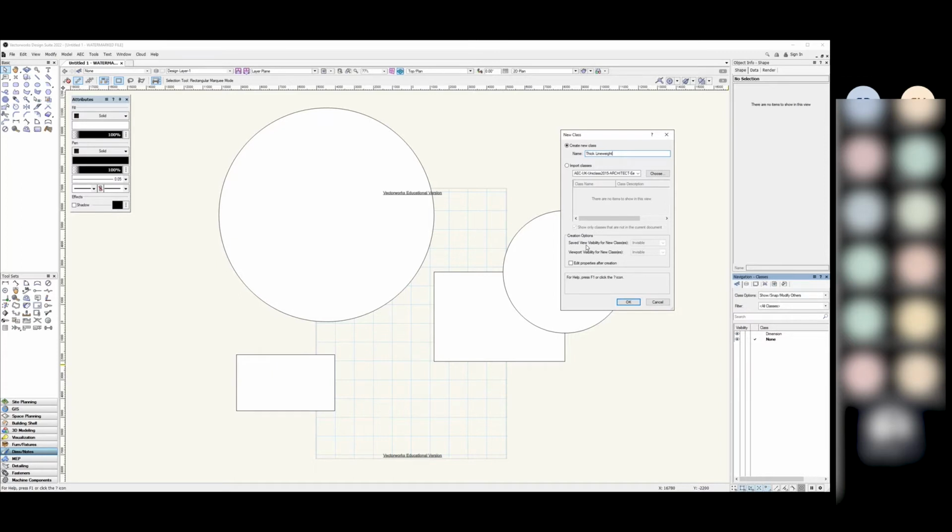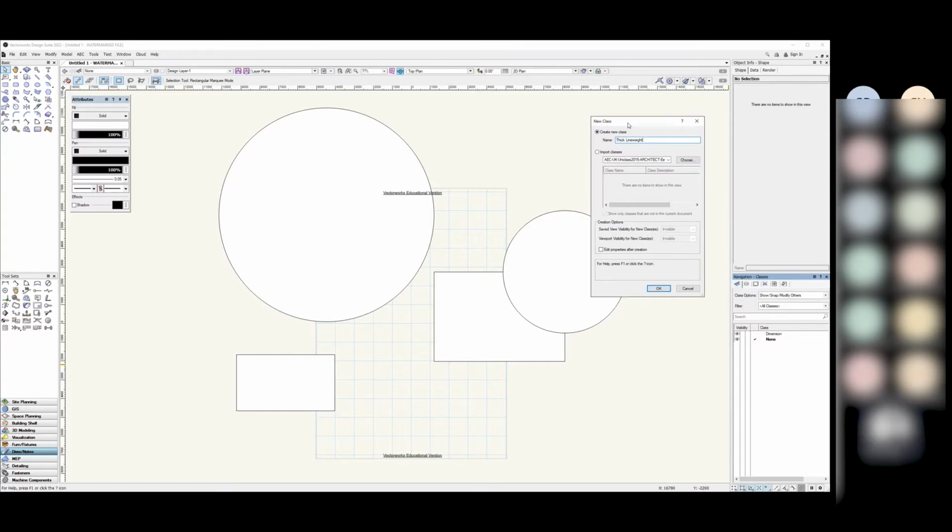It's all about what these line weights are representing. The key thing here is that you're able to differentiate between objects in your drawing. So for instance, anything that's structural, anything that's permanent in your model might have the thickest line weight. Anything that's not a permanent object like furniture might be a thin line weight. Anything that's semi-permanent might be a medium line weight. Anything that's annotative might have its own line weight type, which would be really thin and dashed, for instance. So again, you can have a variety of line weights, but essentially you always want to use a doubling factor when it comes to line weights.